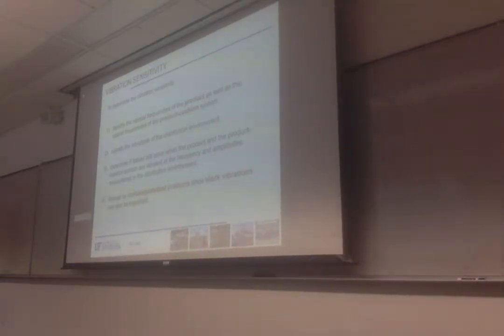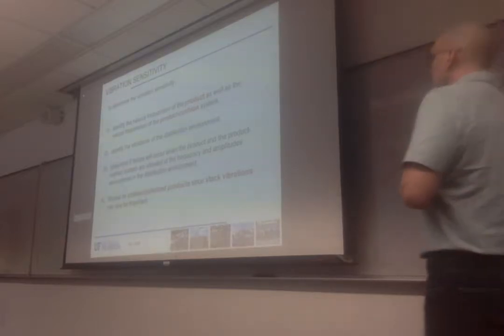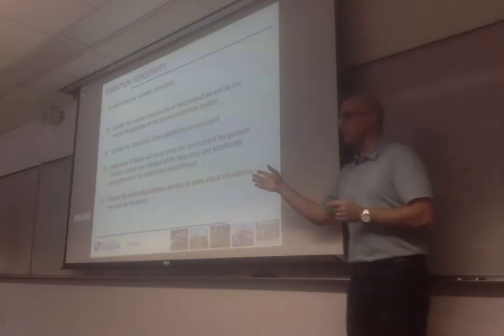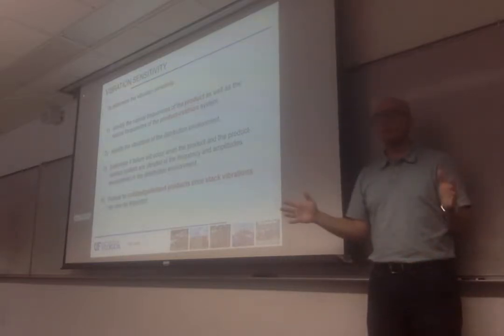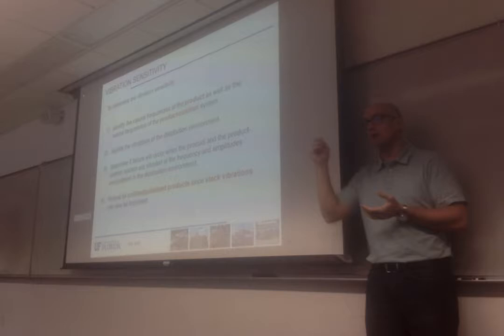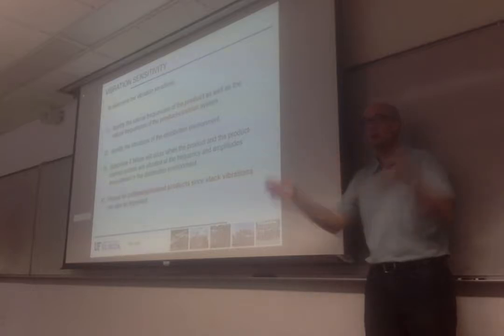In this case, you need to look at stack vibration. If you just stack them or test on a pallet, it's typically impossible to identify the natural frequency of components in your product, but you can see how the stack behaves.